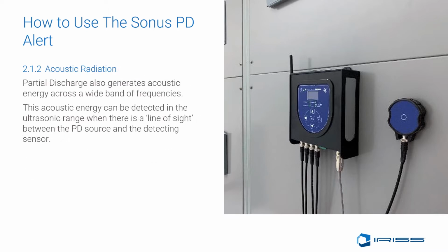Section 2.1.2, Acoustic Radiation. Partial discharge also generates acoustic energy across a wide band of frequency. This acoustic energy can be detected in ultrasonic range when there is a line of sight between the PD source and the detecting sensor.